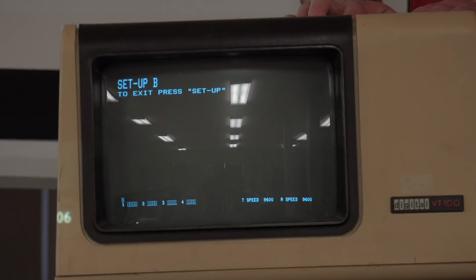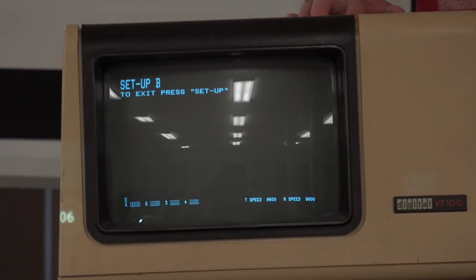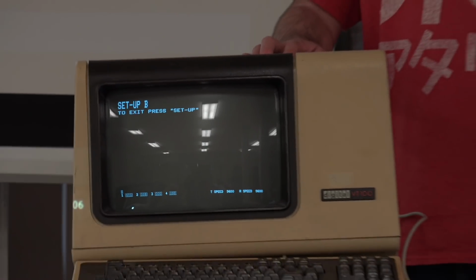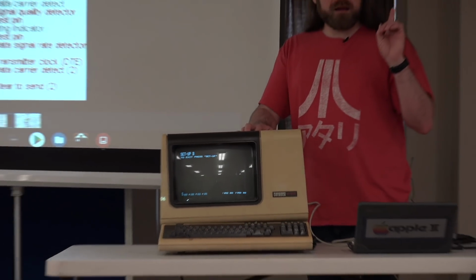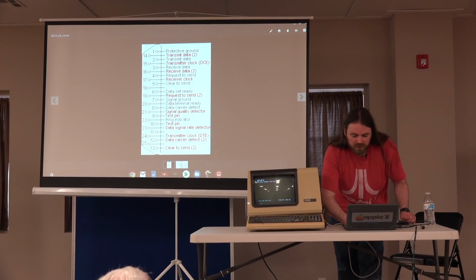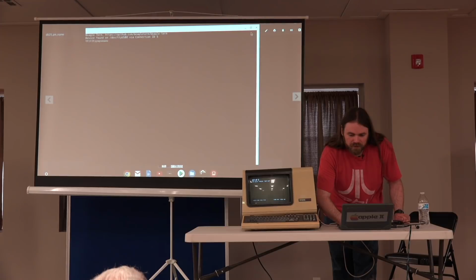It also makes sense that you might get a burst of data from the computer that you're talking to, but the fastest the data going up is going to be as fast as you can type. Yeah, so it wouldn't be as noticeable. But yes, you have to set the speed on both ends. You also have to set the parity and the stop bits, and I clicked through that quickly on the terminal emulator here. If I bring this back up.